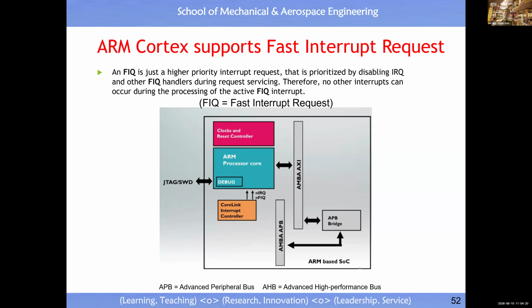An interrupt is an internally generated signal which tells your brain something happened, whether it's empty, full, or whatever. When the microcontroller's program handles or responds to this internal interrupt signal, always remember to clear it after the service, after the response to the interrupt. Otherwise, it will keep responding to the interrupt.